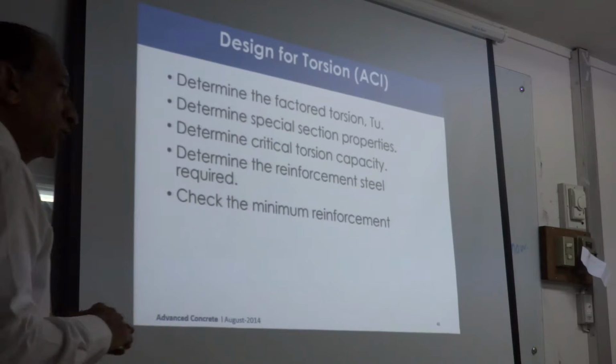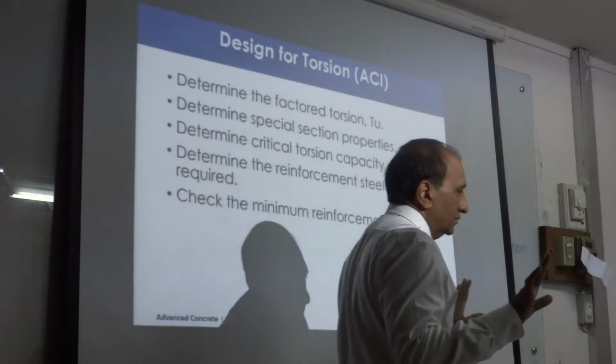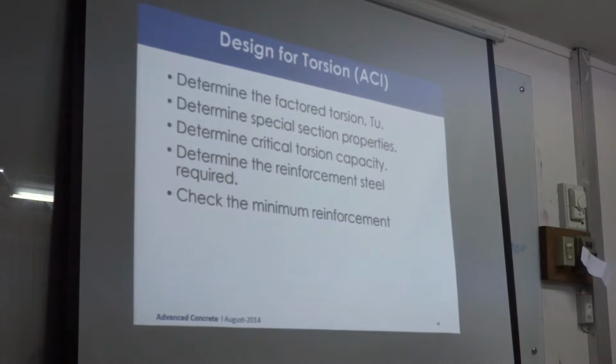Okay, so beam shear. As long as the beam is in Bernoulli's range, we have a very clear formula, the codes are very clear, the procedure is given, and everything is primarily designed based on the Mohr circle concept, right? As soon as we go into the D region, the disturbed region, all of that theory will not work, and we need a different arrangement, which as I said, we will talk about later. So until the midterm, we only talk about normal beam theory.